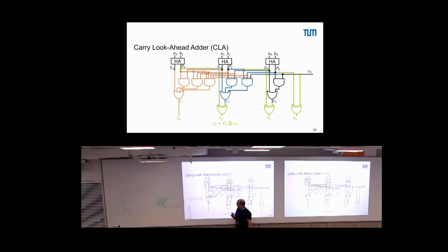No, the most critical thing is, well, in an ideal world, these are ideal switches. In a real world, these are resistive devices, if they are on. So you cannot just stack this, because here, your VDD is fixed, right? Your input here is driven by VDD.